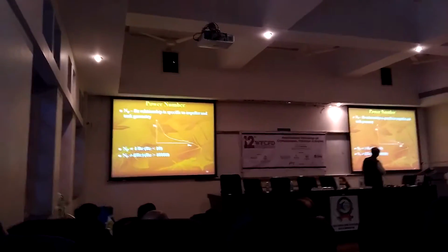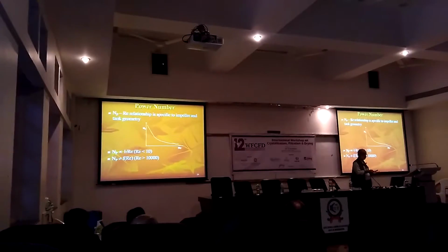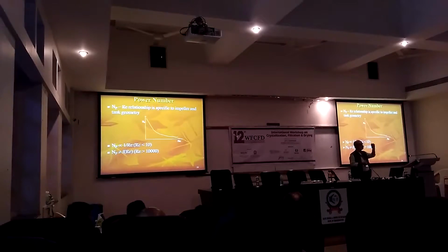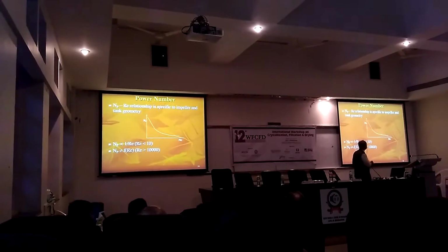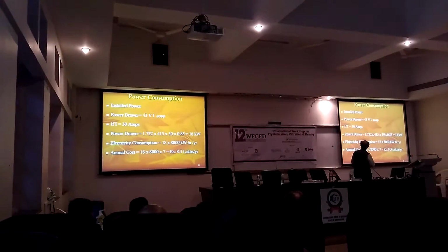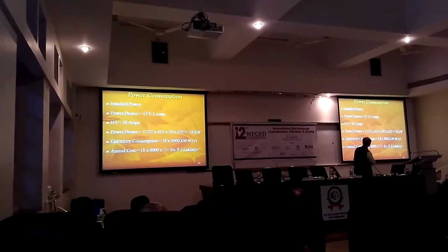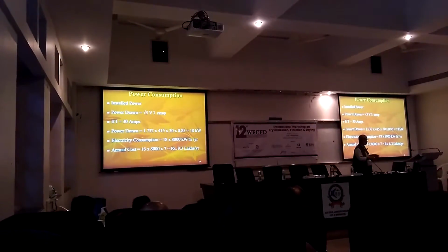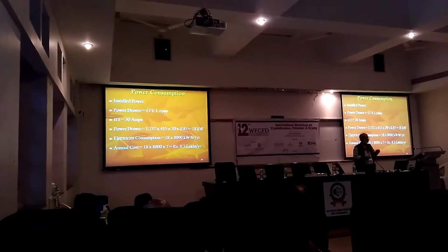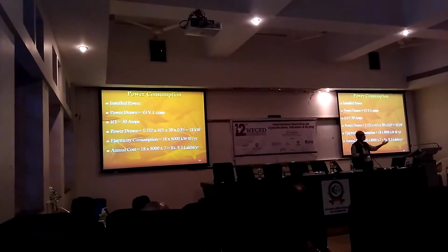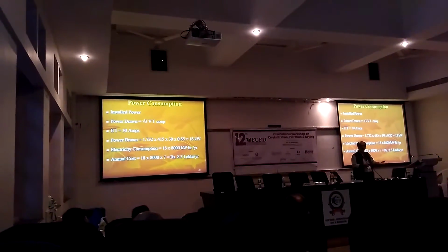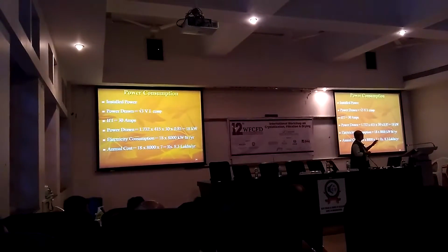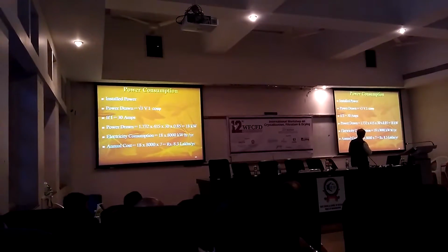You have a laminar regime and you have a turbulent regime, and every impeller or agitator which you choose essentially has the capability of addressing a specific value of power number which can be utilized for the estimation of power dissipation. So this is typical power dissipation. So you can see if you are operating the system, one typical case, we are talking about few lakhs per annum of just the energy associated with the agitation of the power. So the choice of an impeller, operating speed, choice of impeller power number are going to make a big difference as far as your operating expenses are concerned.